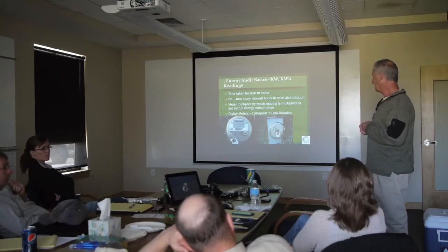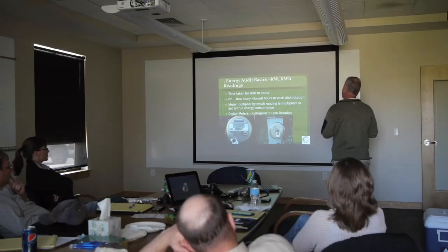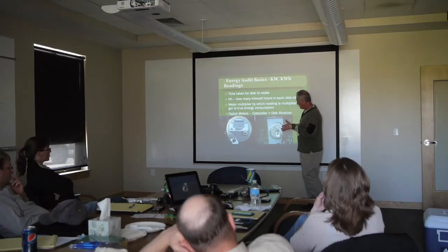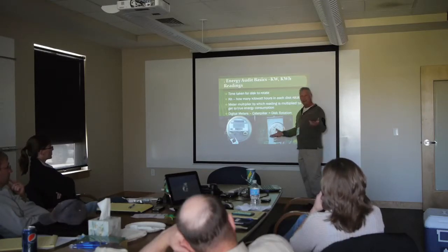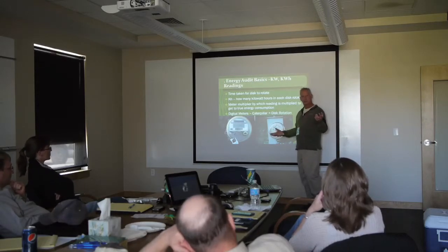You're talking about the one on the right, I assume? Or both of them? The one on the right is a demand meter. It does have energy dials here. But this one is actually a demand meter. It's a mechanical demand meter, and I took a picture of it because I thought it was really cool. I had never seen one. I've seen lots and lots of electronic demand meters, but never a mechanical one. So this big dial is demand, and the little ones are energy.